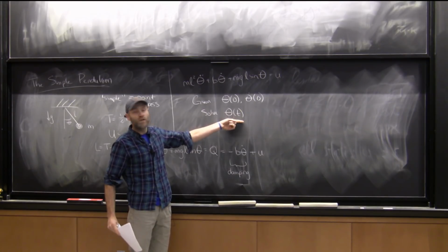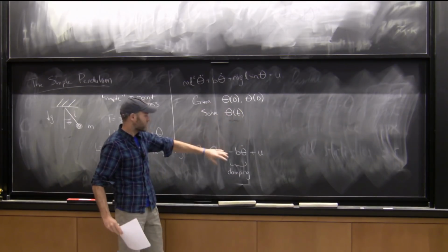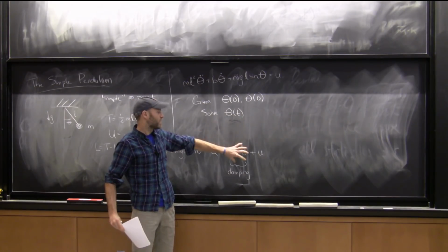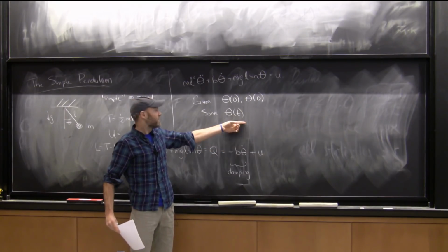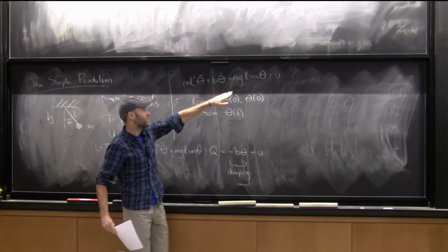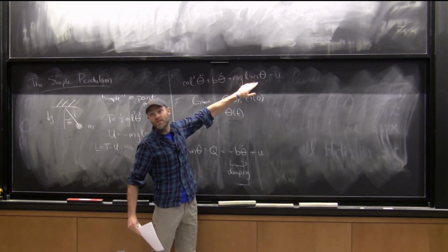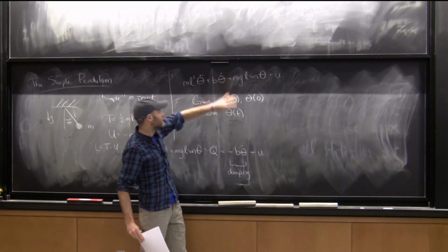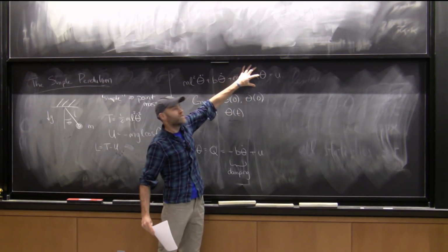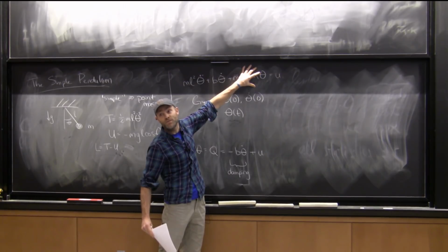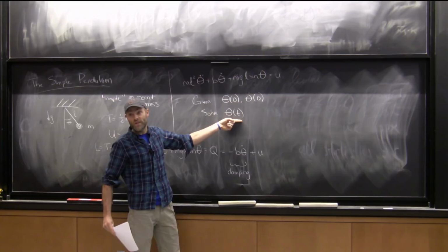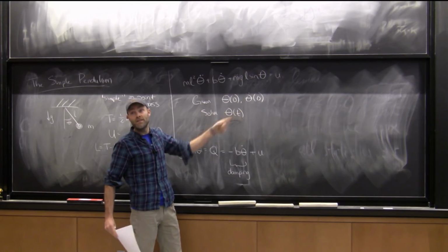So you can write the solution in some cases, if damping is 0, as elliptic integrals of the first kind. You put the damping back in, it gets harder. It turns out that integrating the nonlinear differential equations is actually really hard to do. Right? So everything you did in your DiffEq classes, that term didn't exist. It was a linear differential equation. The nonlinear differential equations, in general, we can't solve.